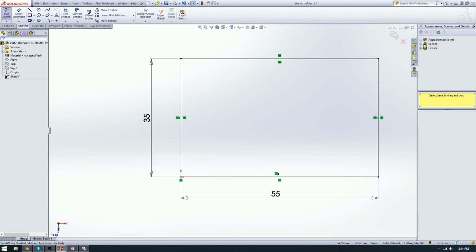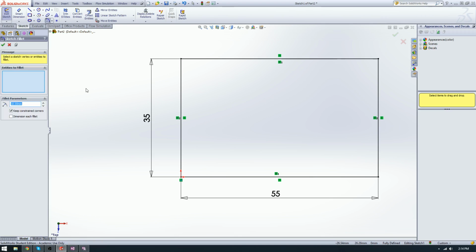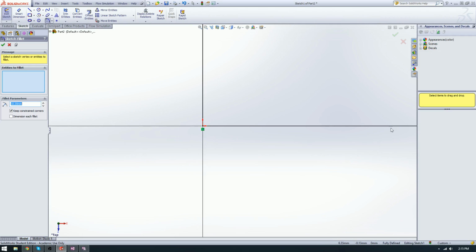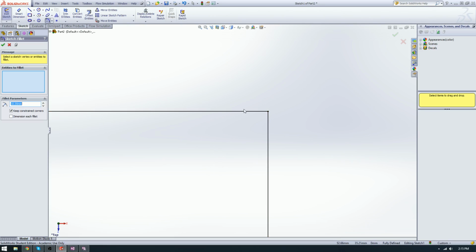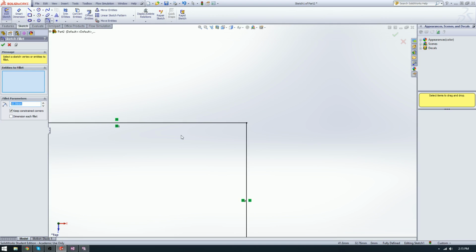So some cool little things we have here. It's called a fillet, and a little side note, it actually comes from the word file, from the old Latin word for file, and intuitively that is kind of what it means. So we have this rough corner here, right? Let's use this corner. Now we want to file this down, so fillet, and we'll go 10 millimeters, so our units are millimeters right now. Let's just leave it at 10.